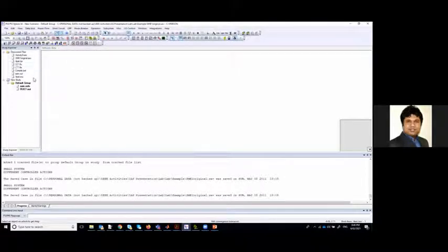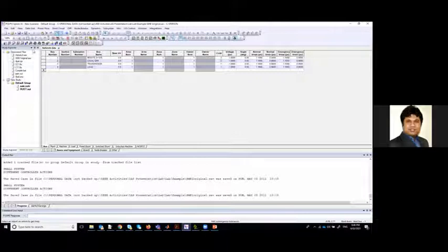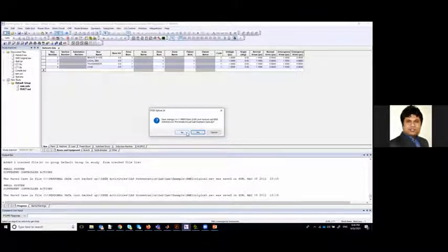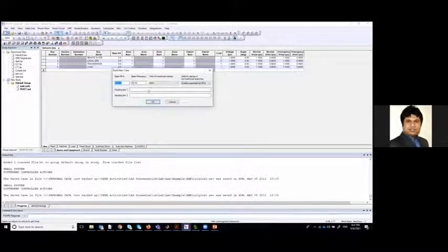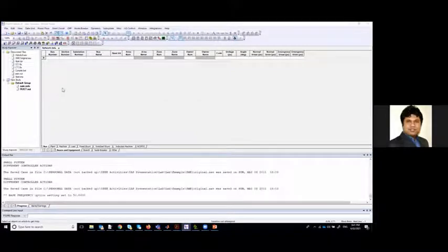I'm going to show you the network data. Let me proceed. So case data. Let's open it. I don't want to save this. When you install it, it asks whether you are going to use 50 Hertz or 60 Hertz. Base MVA is what we need almost. We use 100 MVA by default. That will not affect your simulation anyway. So base frequency, let's say we use 50 Hertz. Okay, so now we got it.